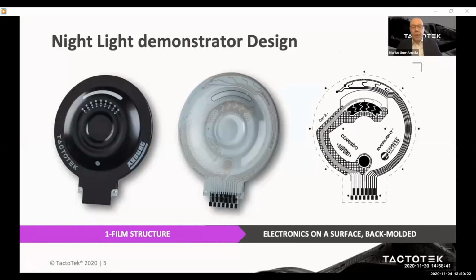The decorative side consists of black and white decorative surfaces for logos, user interface elements, and illuminated window, and the backside in the middle has a functional surface which carries conductive inks, traces, capacitive sensors, and 5 pieces of LED components.